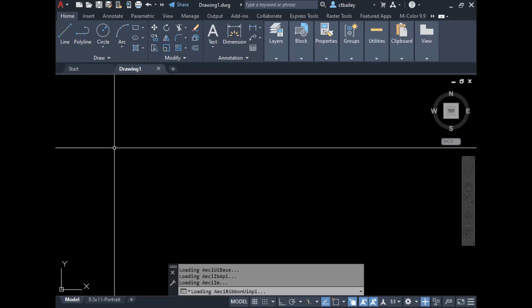Let's say for a second here that we are a millworks company and we have 4 different window styles that we'd like to sell to the customer. Here's my proposal to you: we can do this in 1 block. Once you have that block properly developed, you can just drag it off a tool palette, drop it into your design, and change a couple little parameters and keep moving. You can have double hung on the side. You can have a picture window in the middle. You can change the dimensional sizes. You can change the light styles. You can change everything through the dynamic block system. So that's where I'm going to start my lesson today. I'd like you to just watch a little bit, and then we'll let you guys in on the fun.